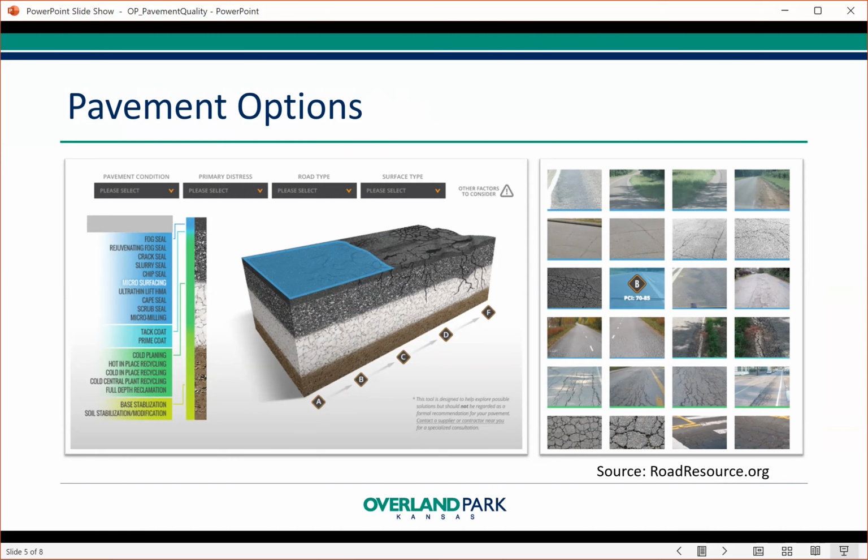Pavement is made up of several layers. The surface course is made from smaller stones to provide a smooth and silent ride. The base course provides the strength with larger rocks. This is laid over an aggregate base, which allows the water to drain away from the asphalt. And the final layer is the subbase, which is the compacted soil underneath the road bed. As the lower levels begin to fail, more elaborate methods are required to restore.